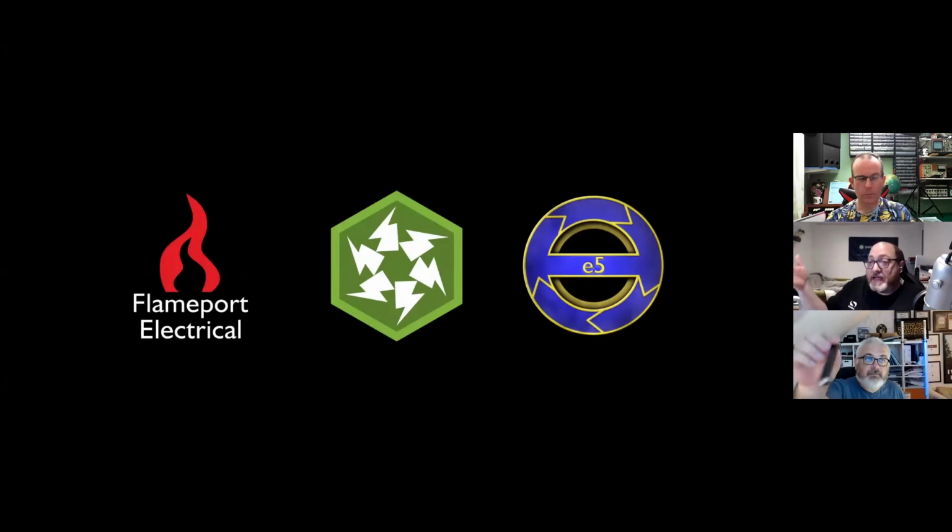Yet we're now being asked to express our opinions on the condition of the installation with no real understanding of what their standards are. And that is the PME supply cable that goes into most houses nowadays. That aluminium core, that copper external. It's tiny. When you think about it, the only thing reliable in that cable is the live. The outer is the neutral and earth. And you can see now why neutral currents may end up getting lost.